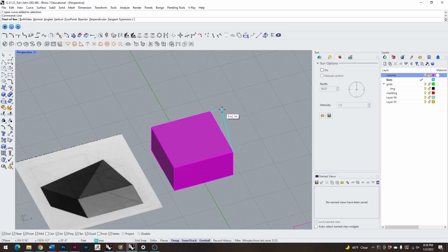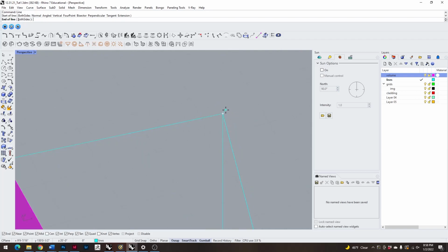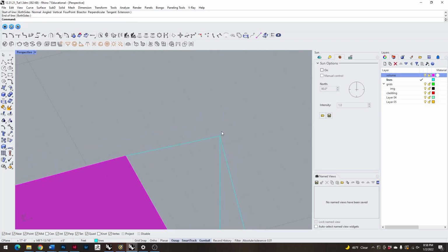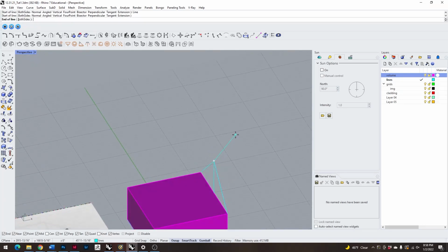So you see how there's this little tag that says end and intersection, and it highlights those lines that I'm connected to. That means that I'm connecting directly to this point. If I'm not doing that, the danger is that it's connecting to some other point, or some point microscopically far away from the end of this line. So my geometries will be broken and dirty, and it won't really work. So keep your snaps in mind.